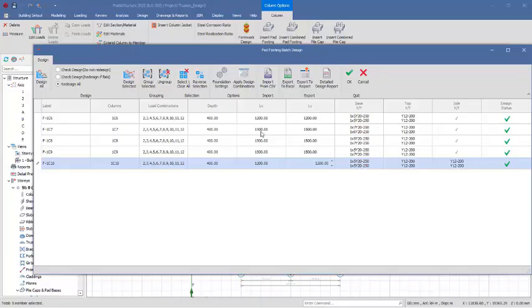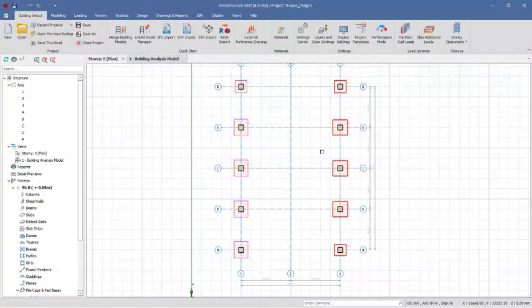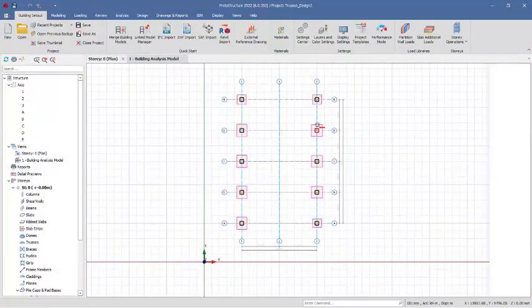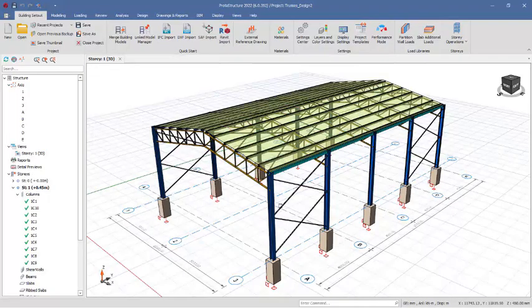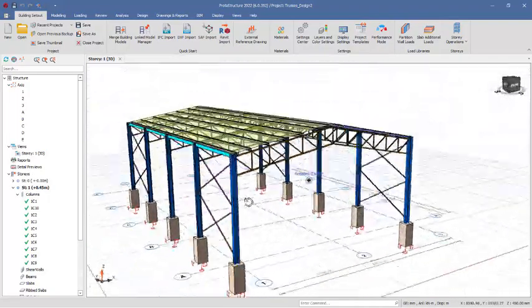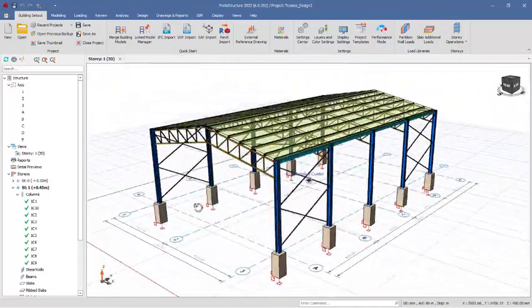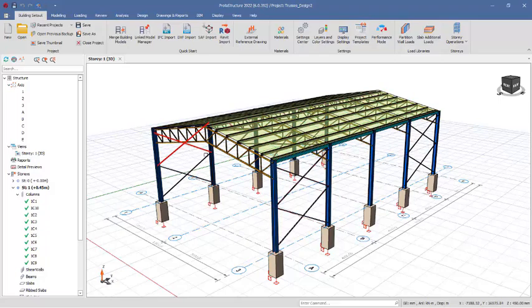You can increase this to 1.2 just like this. So for this one, you have to increase this 1.4 maybe to 1.5 and reduce this to 1.5. It may pass design just like this if you want it to be a square. So for this one I have 1.6, you have to increase this to 1.2. What we will be looking at next is taking it to Protastructure to design the connection successfully.